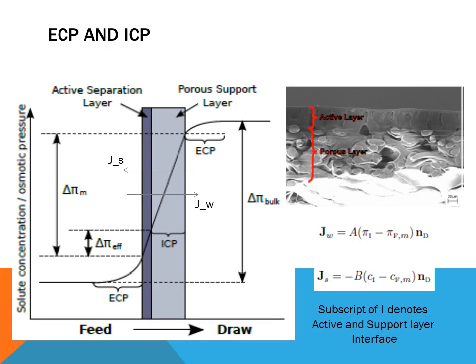So you get a strong concentration of water right here that really dilutes the draw solution. So over this one little membrane part, you're going to only see about this much effective osmotic pressure, and your ability to transport water from one side to the other is drastically decreased.